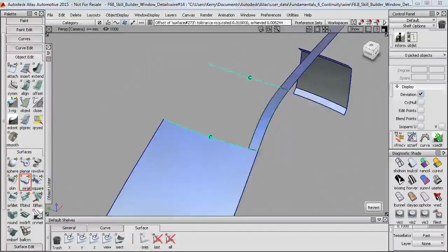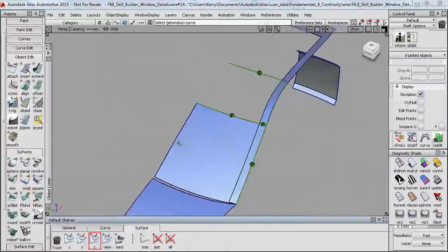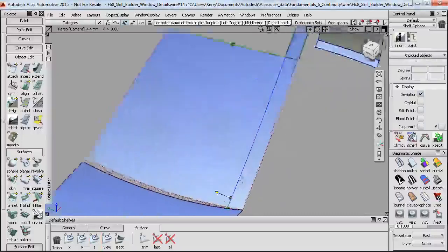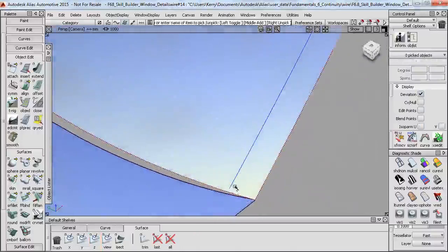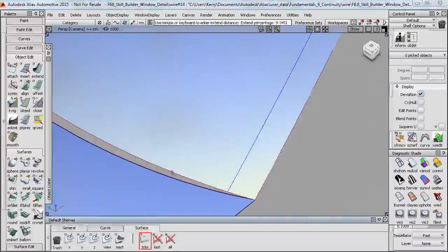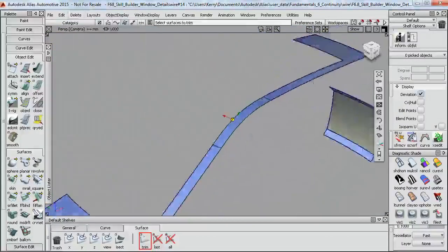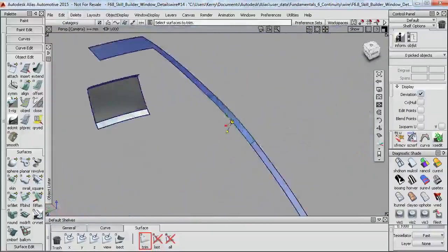And I can just do the same again here on the windscreen surface. But you might want to think of a different way, maybe using curves and the offset tool. And it's a good idea to try lots of different ways and work out which one was the most efficient. Now down here, my curve on surface doesn't quite go far enough. So I'll just use the extend tool to take that all the way to the edge. And then I can trim the middle part away. So I don't need those locators, but now I've got my outer edge.